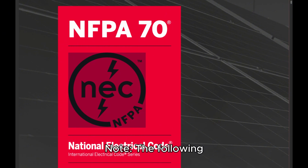CMP14 informational note. The following apparatus are examples of simple apparatus. 1, passive components, for example, switches, junction boxes, resistance temperature devices, and simple semiconductor devices such as LEDs. 2, sources of stored energy consisting of single components in simple circuits with well-defined parameters, for example, capacitors or inductors, whose values are considered when determining the overall safety of the system. 3, sources of generated energy, for example, thermocouples and photocells that do not generate more than 1.5 volts, 100 milliamperes, and 25 milliwatts. Special permission, the written consent of the authority having jurisdiction.